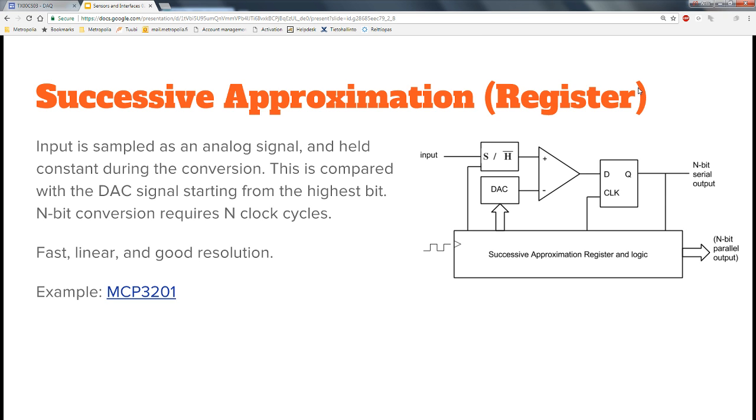This is kind of midway technology, successive approximation. It is the successive approximation register type of A to D converter, where you can have a relatively high sampling rate and high precision at the same time. So basically, there is a D to A converter and a digital logic that flips some bits on the D to A. D to A's are quite simple to make with a high precision.